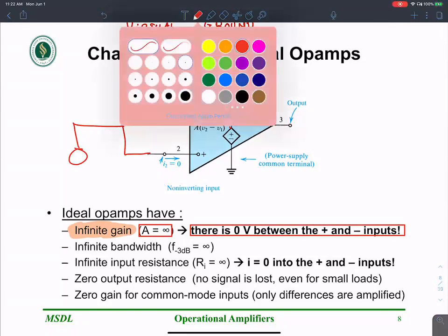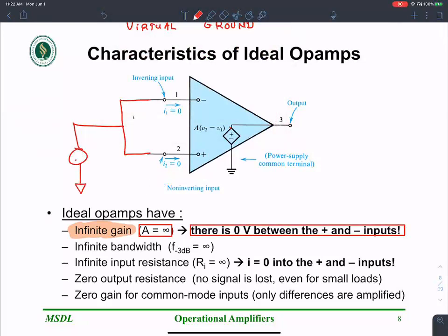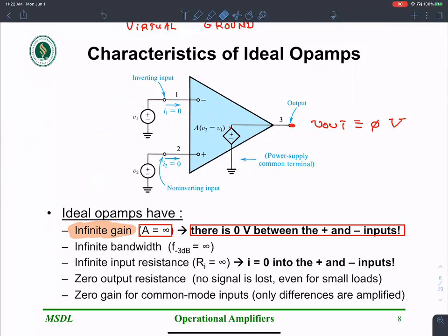If you tie both of the inputs like so, and you apply a common mode voltage that is common to both the terminals, the output is going to be zero. Okay, thank you. I'm sorry I did not get your question earlier. So that's the idea. Only the voltage between these two terminals is